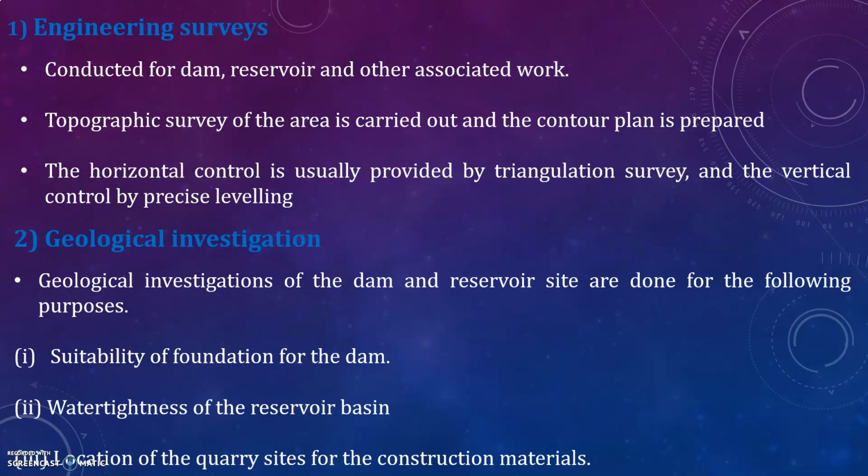In almost all major civil engineering projects, geological advice is the most essential. Geological investigations cost very little in comparison to the total cost of the project. In a number of cases in recent years, it has amounted to between 1/4 to 1% of the whole. This relatively small amount represents a valuable insurance against expensive difficulties otherwise unforeseen which might arise during construction, but which it may be possible to predict from a study of the geological factors involved.